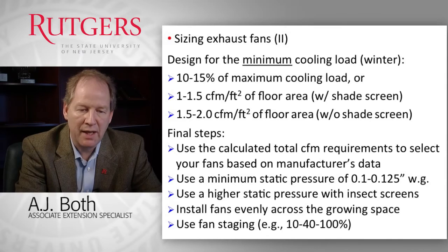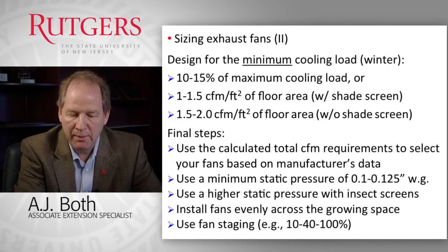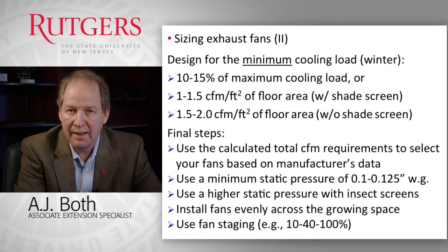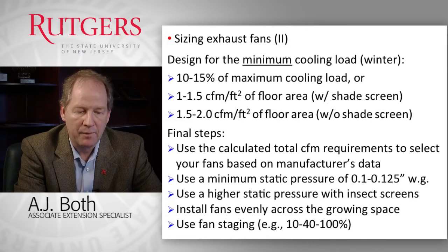So after you made those calculations, you have your maximum cooling capacity requirement, you have your minimum cooling capacity requirement. You can then go to manufacturers' published data, their brochures, and look at different capacities and different sizes and different static pressures they're able to overcome. And you can start making selections.